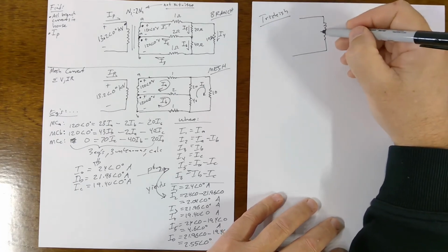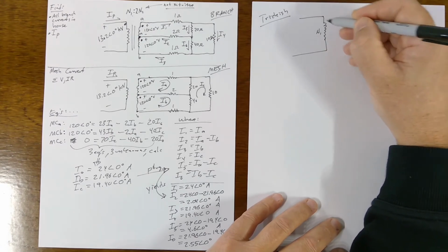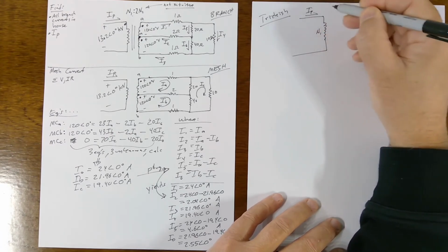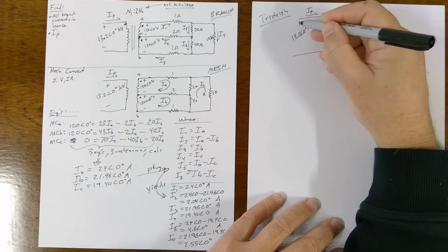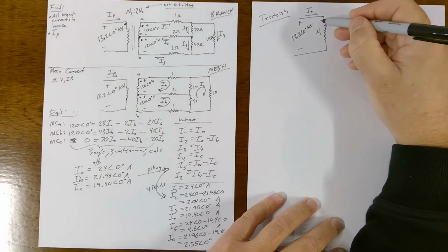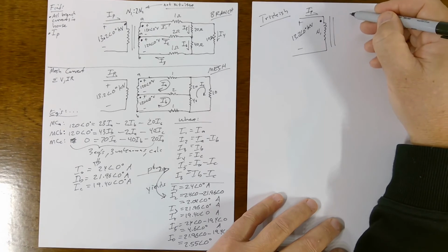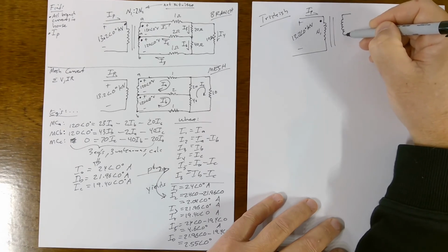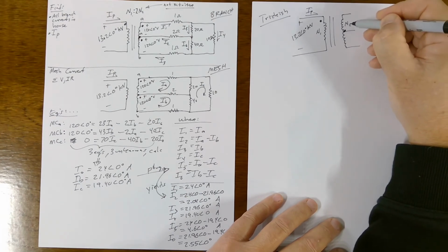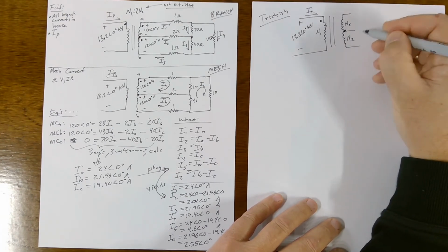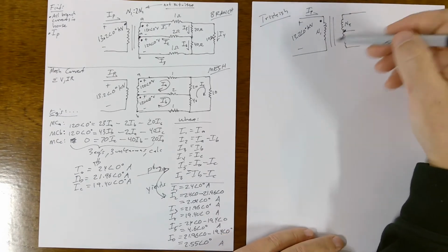Why not? So we've got N1 windings here, and we've got IP going through this guy at the 13.2 angle 0 degrees kilovolts, this polarity. We've got a dot. Then we've got a chunk of iron in there, and then we've got a winding that's split in half, and there's N2 turns here and N2 turns here. The reason for splitting this up is it makes the solution easier.